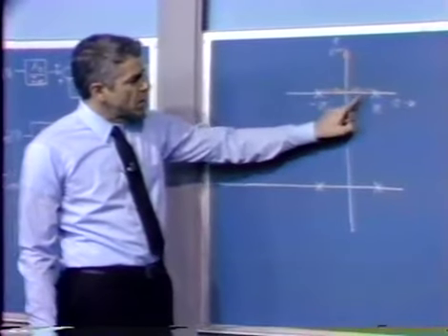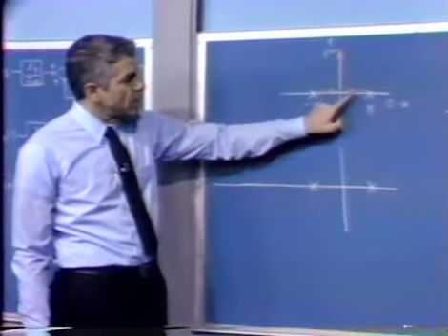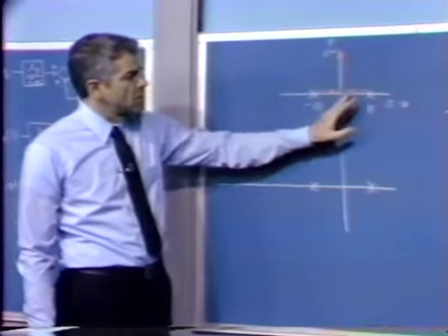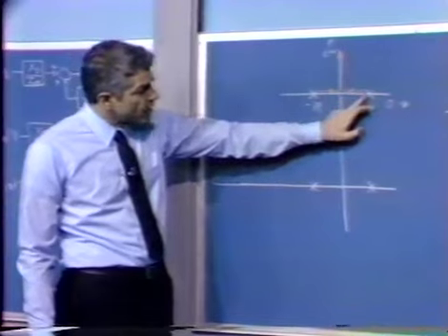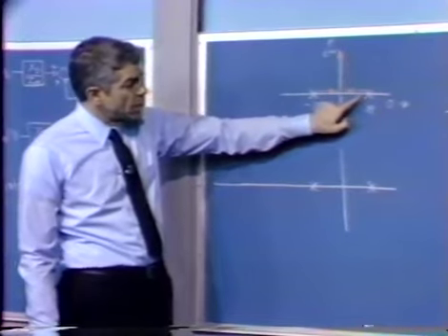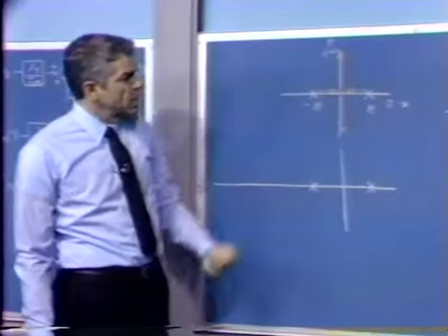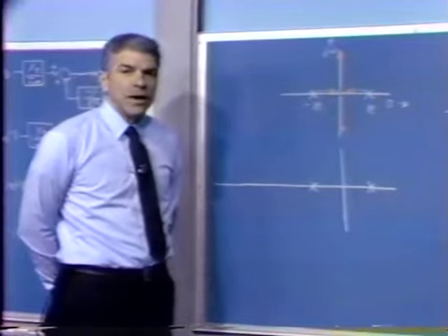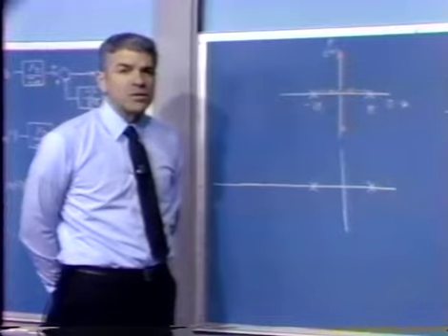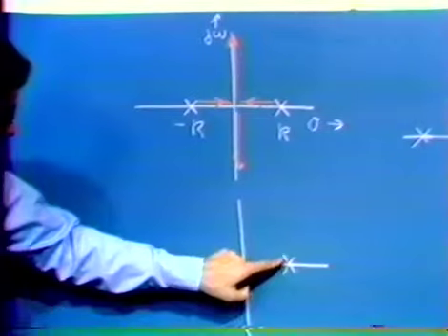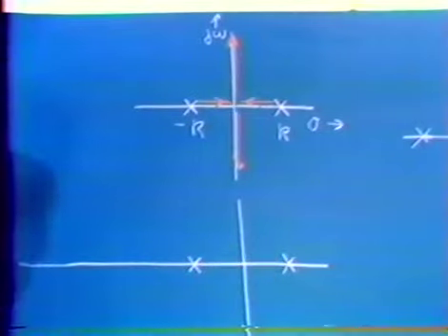If we start with a low value for A naught, we just don't move this pole even to the imaginary axis. And again, while we can bring this pole left, it still remains in the right half plane. And so this is a system where lowering loop transmission magnitude, which for many systems at least results in stable performance, fails. Well, let's see. Suppose we add a zero. That's a good thing to do. And in fact,